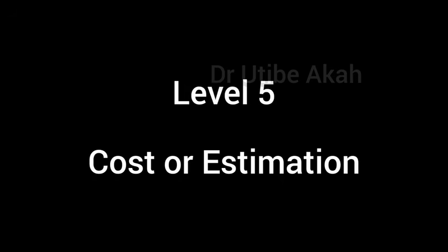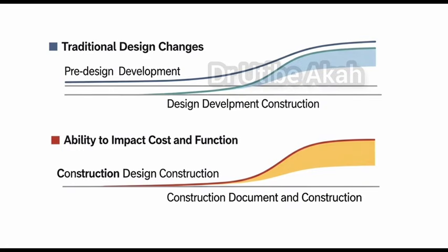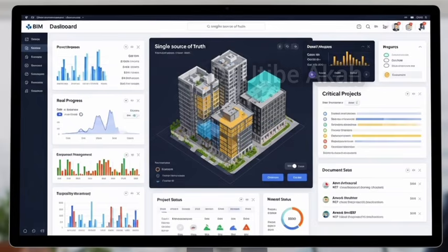5D, cost or estimation. In Nigeria, inflation is a reality. If the price of cement jumps by 20% overnight, a 5D BIM model can tell you exactly how that impacts the total project cost within minutes, because the software knows the exact volume of every concrete element.